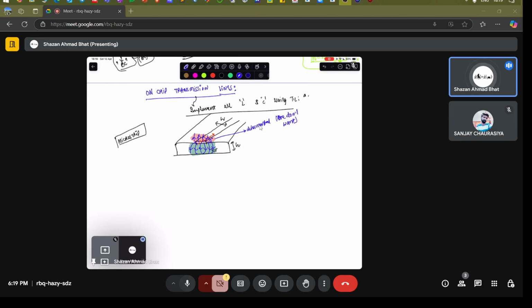Now, you talked about previously, for example, this is air with permittivity epsilon one, and this is epsilon r. Then you talk about something called the effective refractive index, wherein you talk about both of the refractive indices simultaneously because of this leaking field into the air. So part of the electromagnetic wave is in the air, part of it is in the dielectric. So you define something called the effective refractive index.